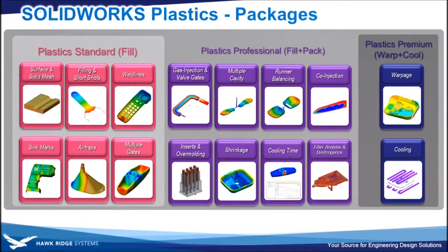that doesn't really have any knowledge or input on the mold setup. Plastics Professional, which is the middle package there, would be the minimum level of the software required to do any of these kinds of simulation with insert overmolding, being able to specify that there's an existing insert of a different material in the mold.